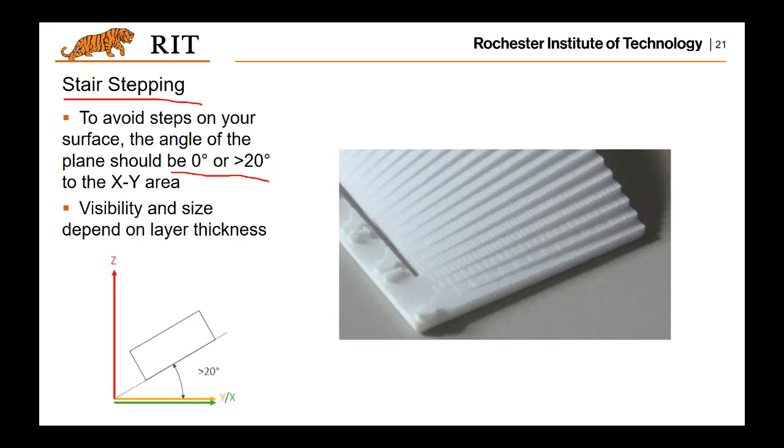So if you look at this illustration, you want to tilt your plane with respect to X and Y only to be either parallel or larger than 20 degrees. That's the restriction. Otherwise, there will be a visible, quite significant stair-stepping effect on your part.